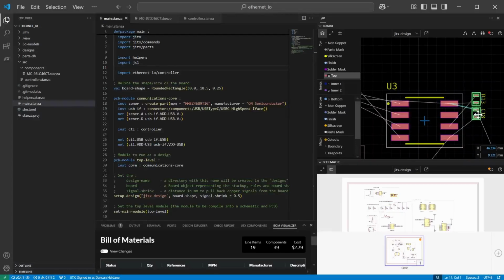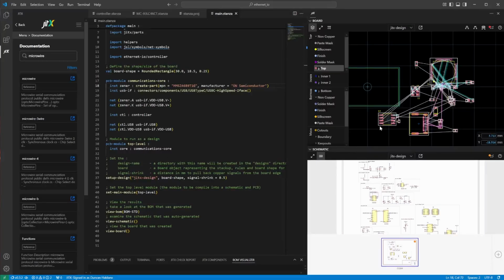So here's our subcircuit, and with that, you've learned how to make custom components and circuits from scratch. This training covered all of the basic coding practices you need to use JITX. We learned how to sketch out a design using code, so you and your team can stay organized and collaborate, how to add components from our online database of several million parts, how to find and use circuits from libraries, how to model components from scratch, using that EEPROM as an example, and then how to make a reusable circuit for that EEPROM using nets, ports, and bundles. And finally, we also covered how to automate the selection of parts using the pull-up resistor and the bypass capacitor as examples.